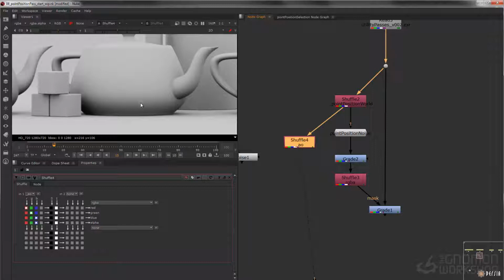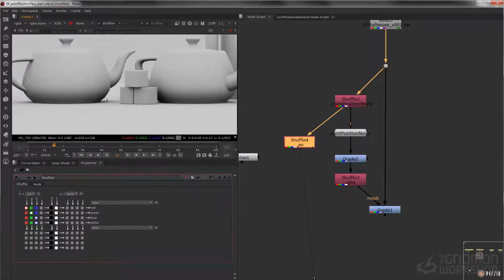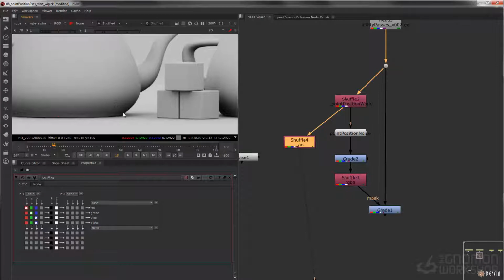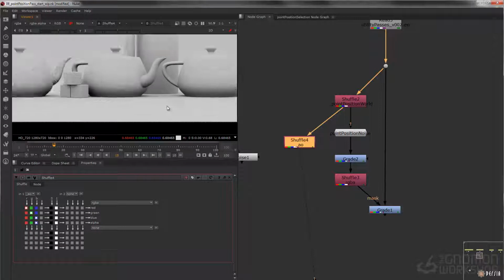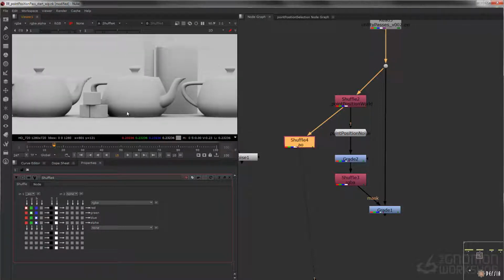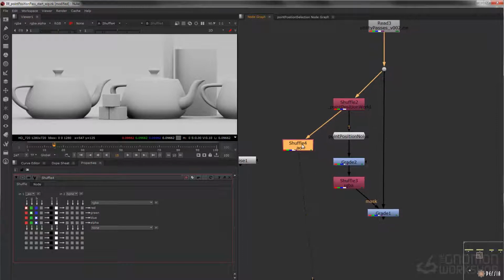And essentially what's happening here is ambient occlusion, the way it works is it's essentially ray trace information, but it's essentially distance away from each other. So if an object is touching an object, it's going to return a black value. And then the further away it gets, it's going to return a 1 value. So it's really just kind of like a contact shadow. And we can utilize this with our RGB setup.